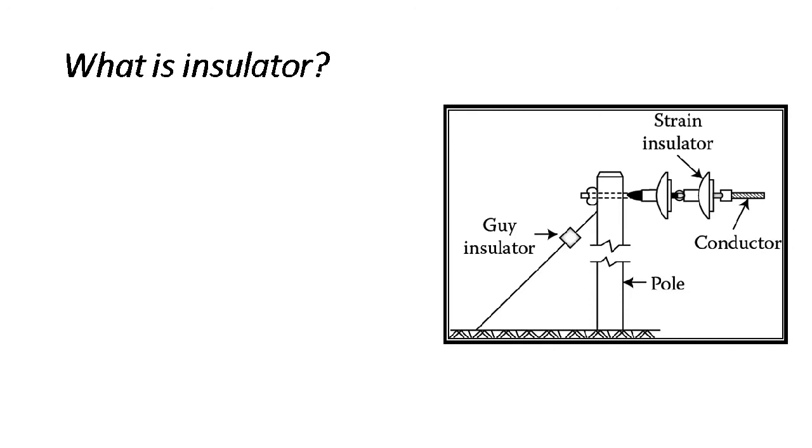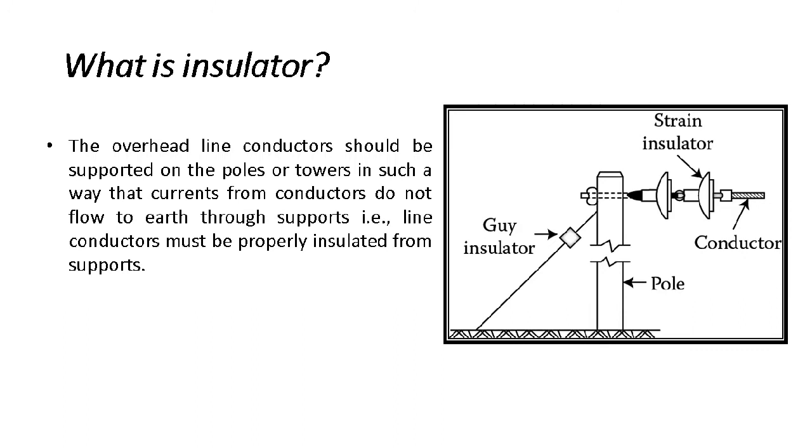An electrical insulator is a material whose internal electric charges do not flow freely. It means very little electric current will flow through it under the influence of an electrical field. A perfect insulator does not exist because even an insulator contains a very small number of carrier charges, which can help the current to flow. In addition, all insulators become electrically conductive when a sufficiently large voltage is applied. The electric field tears the electrons away from the atoms, and this is known as the breakdown voltage of any kind of insulator.